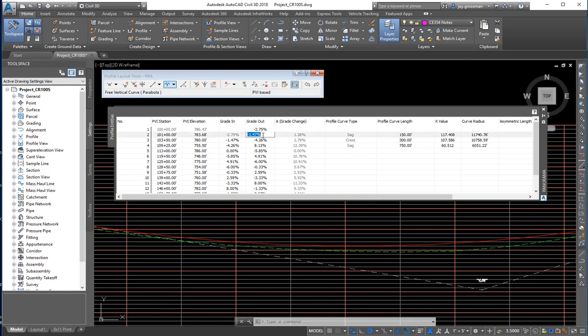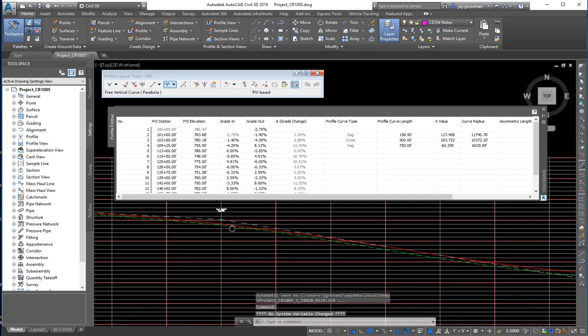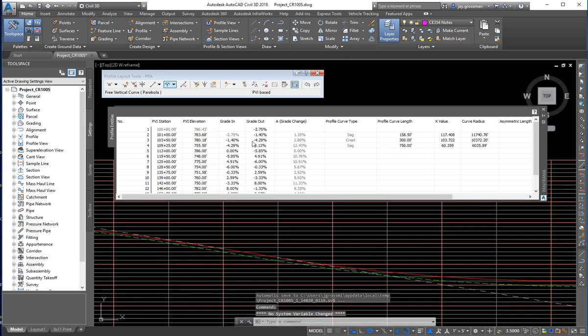Let's set our outbound. We can also set our grade. Let's say we don't want to go anything above a negative 1.4. That'll force it up a little bit. Oh, I typed in the wrong one. I just set that grade. Bad. Okay. And we come through here, and then we get this -4. That's the bad one. So coming out of that last one before this, let's set it at -4.25. That'll raise it up a little.